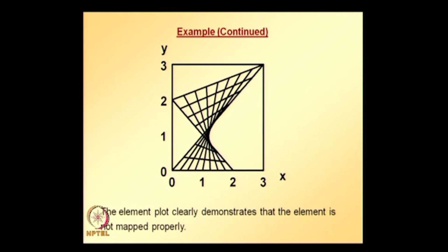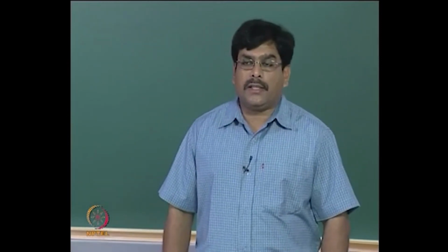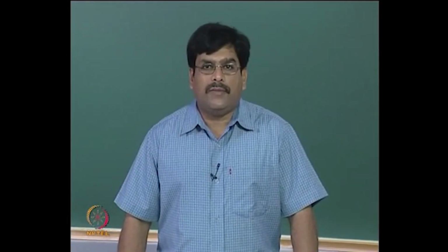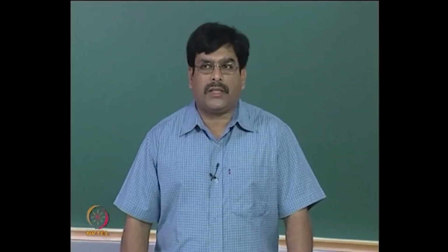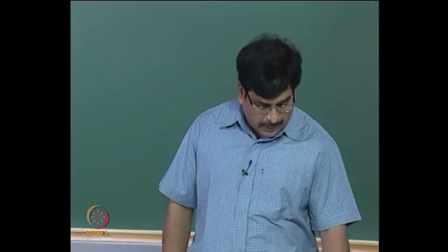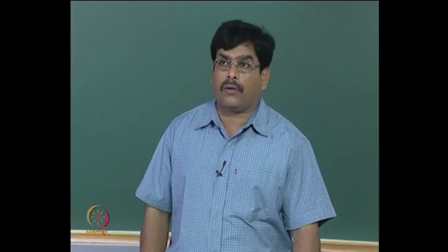numerical integration for quadrilateral elements, because for the matrices and vectors that we are going to get for quadrilateral elements, the integrand for the integrals is not going to be a constant like in the 3 node triangular element, which is linear, but a function of x and y, or in turn a function of S and T. So, when we are trying to evaluate these integrals, we need to adopt numerical integration, because we may not be able to find the closed form expressions so easily, because the integrand becomes complicated. So, now let us look at numerical integration for quadrilateral elements.